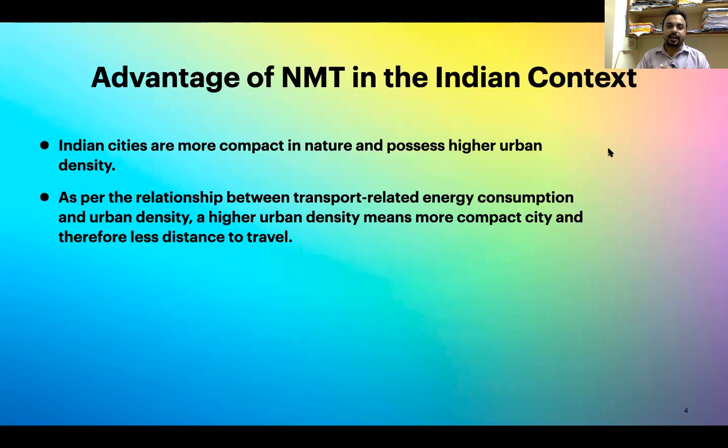So what are the advantages of non-motorized transportation in the Indian context? I've already said that Indian cities are more compact in nature and possess higher urban density. As per the relationship between transport-related energy consumption and urban density, a higher urban density means a more compact city and therefore less distance to travel. So when you have less distance to travel in a compact city, you will be more prone to use non-motorized transportation.